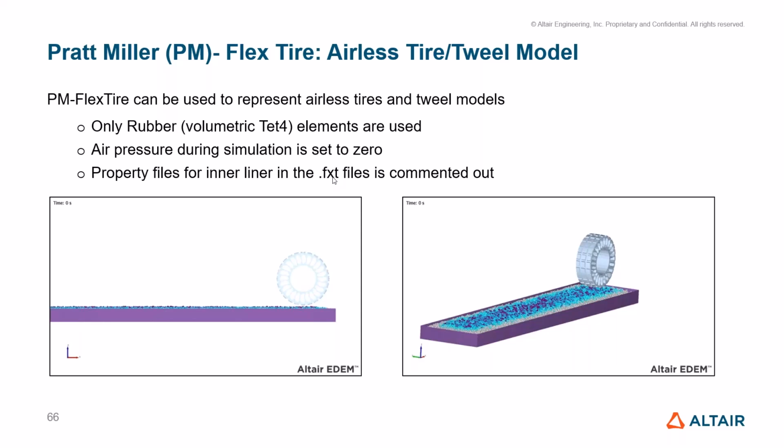For example, for metallic conditions, fatigue calculation helps us figure out the life. But for the tire, if you say life, what is the parameter you verify? Based on that, we can recommend the methodology. For example, if you consider tire tread wear, then we have direct wear measurements. Apart from that, we don't have any other measurement to assess the life of the tire.